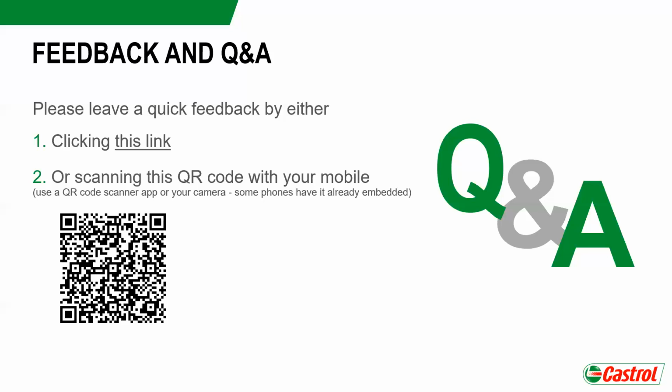Are there any instances where PD technology can cause harm to the equipment? Yeah, thank you very much, Petros. So there is one specific example that I can think of from a practical perspective. Depending on the type of gearbox that you have, sometimes you have things called internal backstops present. Now, a backstop will prevent the shaft from rotating in the wrong direction. So it's a bit like a freewheeling or overrunning clutch, if you like.